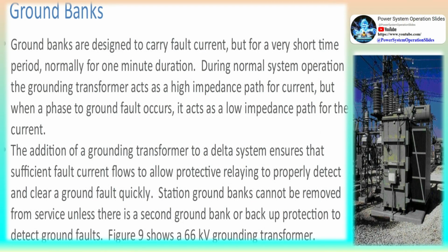Typical application cases. CTs are commonly used for current monitoring and overload protection, such as measuring the secondary current of transformers. PTs are used for voltage measurement, such as measuring voltage on high voltage lines or providing voltage signals to relays.